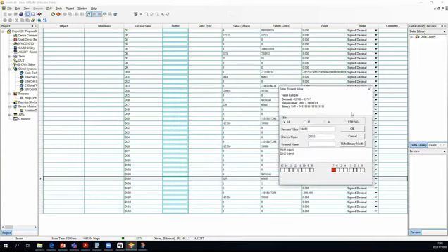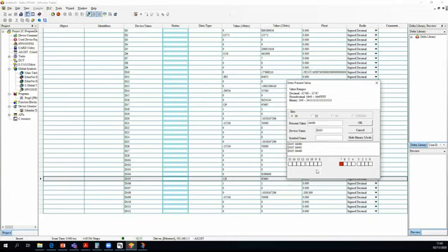So yeah, now if I just give the drive a run command, you can actually see the drive moving to its target position. If I give it another run, you can see it actually moved, this time to position 100,000. I'm giving it 50,000 pulses, so the drive is moving in relative movement every time I give it the command to move to a new position.